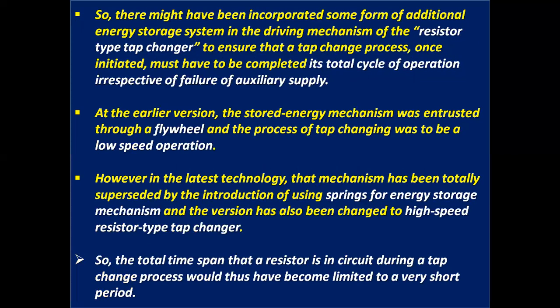So, some form of additional energy storage system is incorporated in the driving mechanism of the resistor type tap changer to ensure that a tap change process, once initiated, must complete its total cycle of operation irrespective of failure of auxiliary supply.